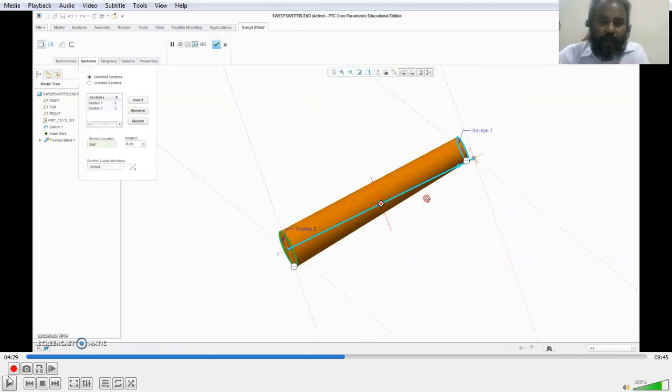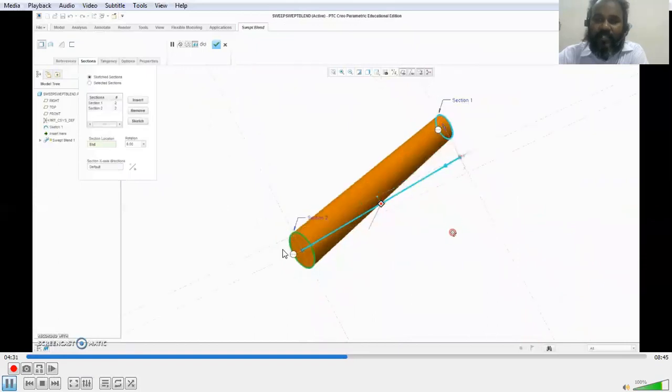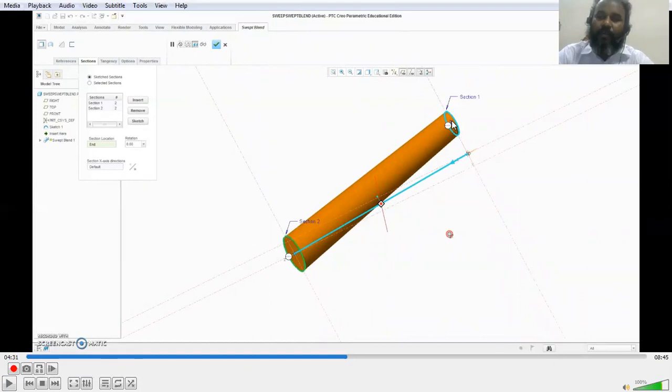But you can see an error here. So what is the error? The center line that I drew, the first thing that I drew, the straight line, is here, the blue color line, but the sketch is formed somewhere else, a misaligned sketch. The blend has happened at a different point because I chose the center point of this circle, this section, away from the end point of the line. That was a judgmental error that I made, because of which I've got a skewed nozzle.